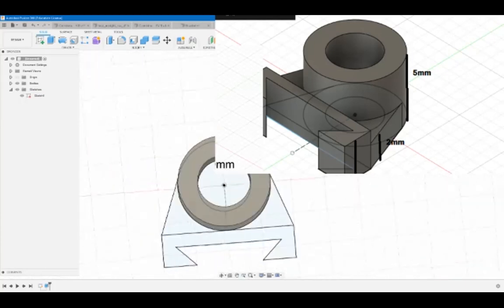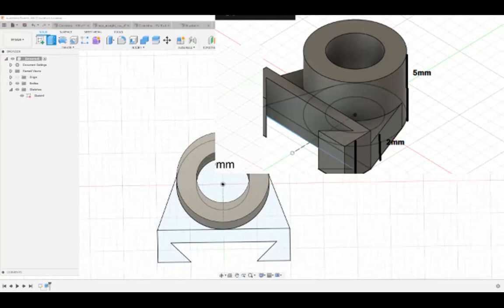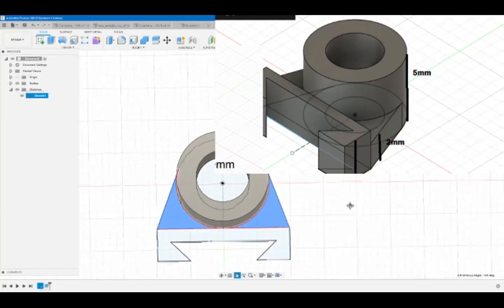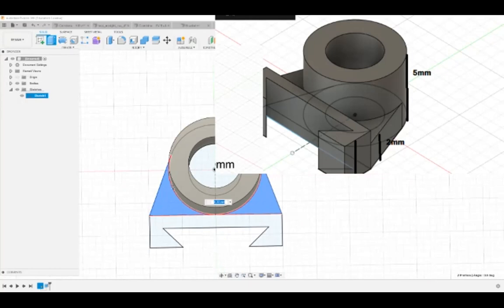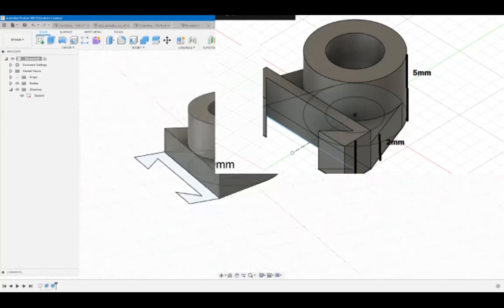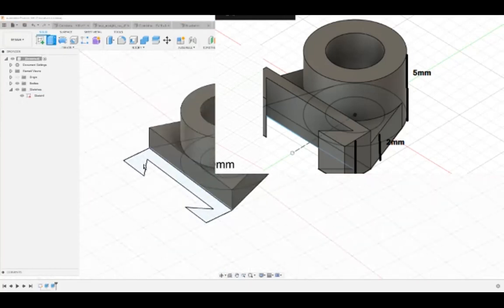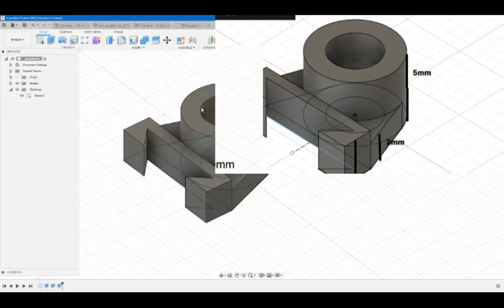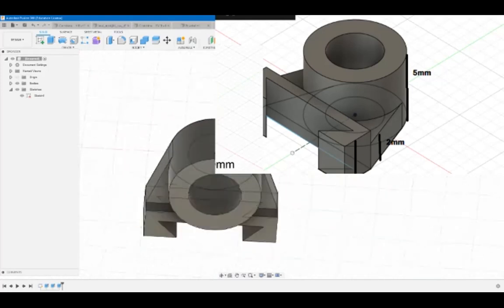So with that in mind, you can go to your extrusion and pick another contour, or you can pick multiple contours if you hold Shift and then click a second one, and specify here, 2 millimeters. So we can extrude this one by 2 millimeters. And now we have another one. And once again, we can do the same thing one more time on this third one and extrude this one by, I think I specified 3 or 4. I don't honestly remember the value. I just kind of picked them at random for the sake of demonstration. And now we have our nice little concise part.